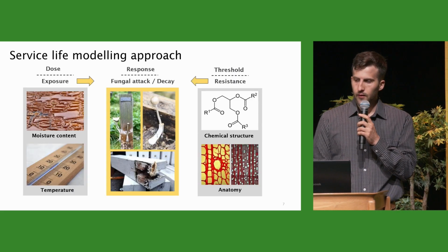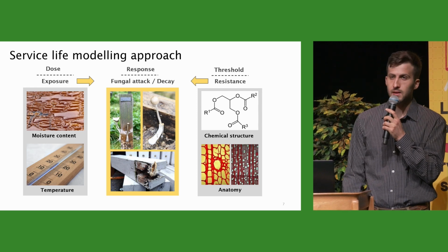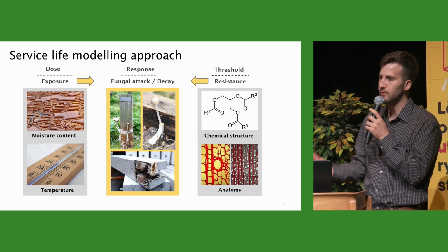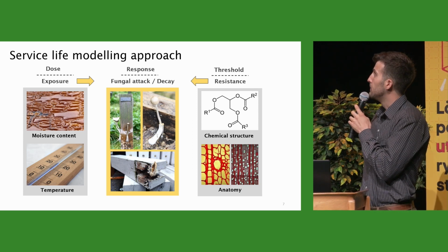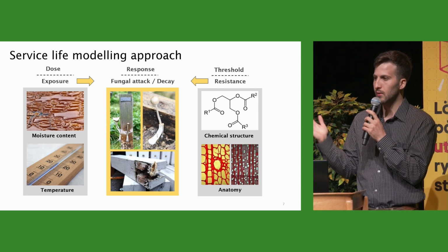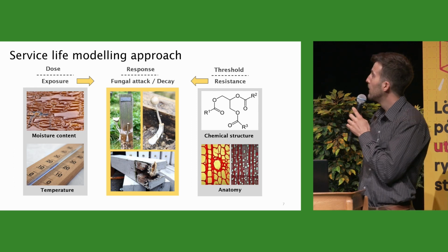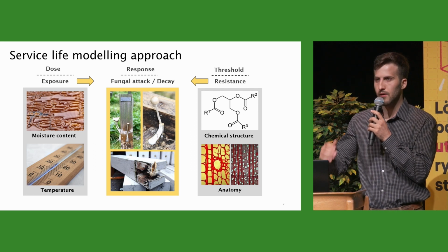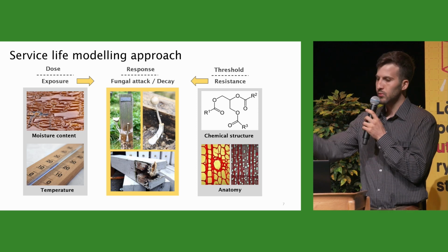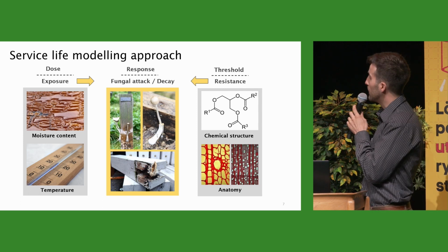And if you consider fungal decay specifically, then exposure for us means moisture and temperature, and that can create something which we refer to as a dose. And if you have enough periods of dose, or accumulation of dose, you can expect a response in the form of fungal decay. And so if you then have a material that has specific durability characteristics, that will influence the threshold of how much of this dose exposure it can handle.